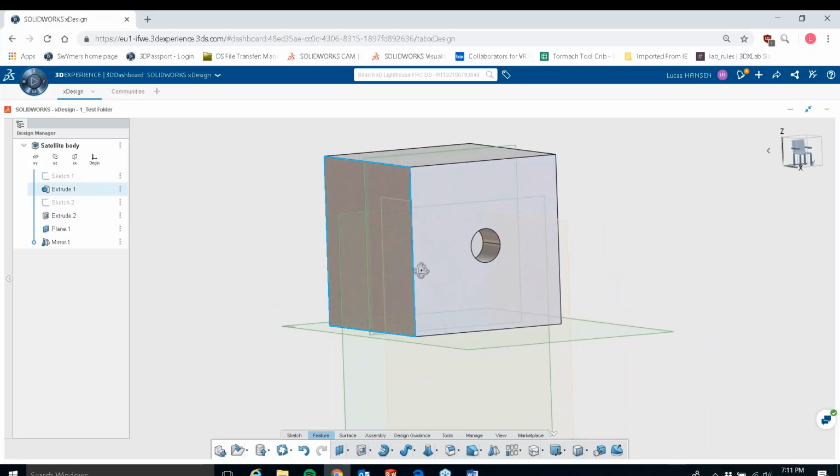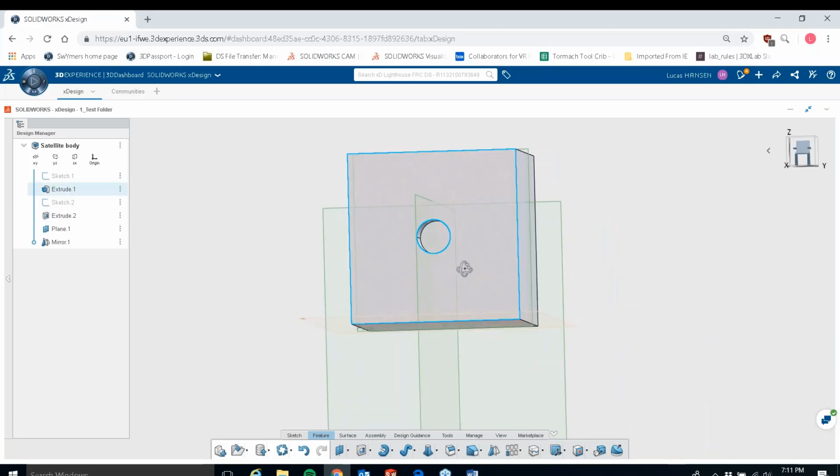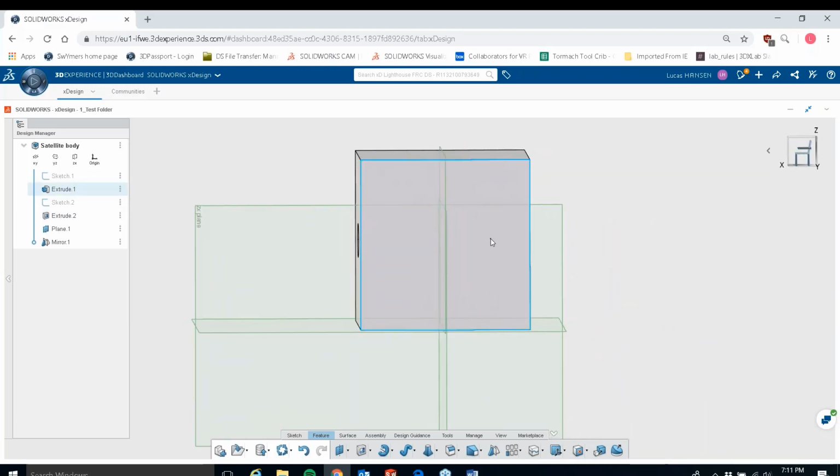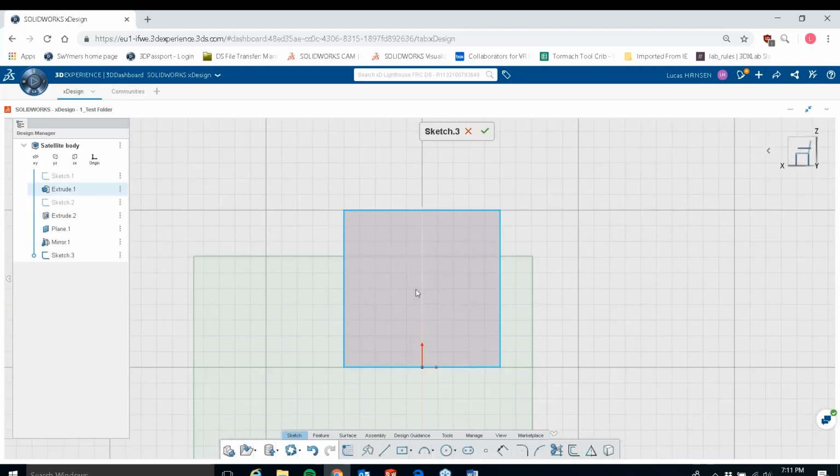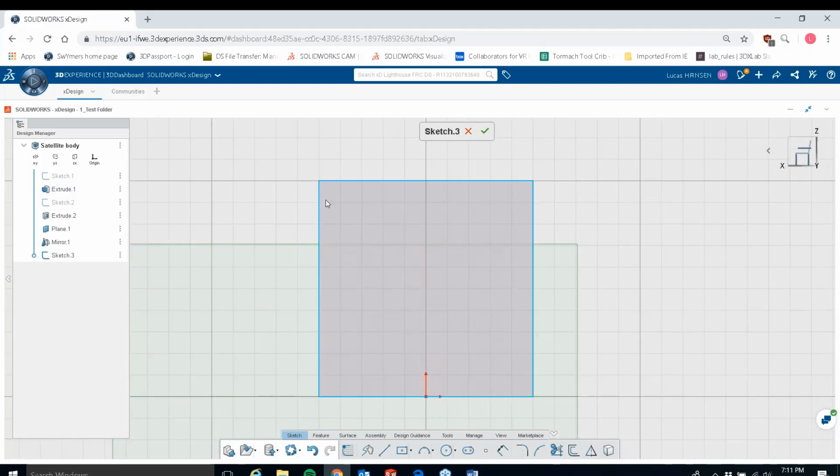So now we have both of the mounting locations done. I'm going to go ahead and on the back side of this create an expansion bay, if you will. We're going to do the same process. Click on the face that we want to begin sketching on. Click Edit Sketch. That's going to bring us normal to the plane there. We're going to use our circle tool again. I'm going to go from the middle of this.